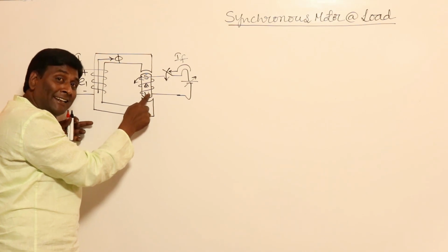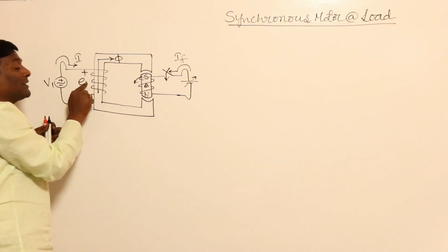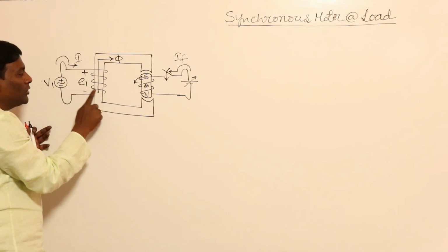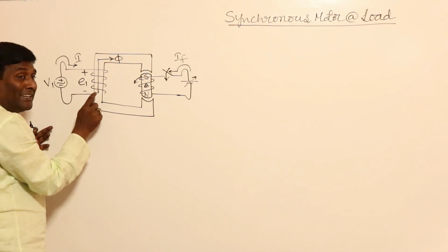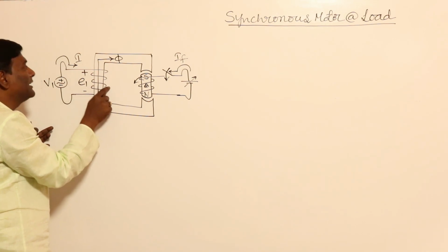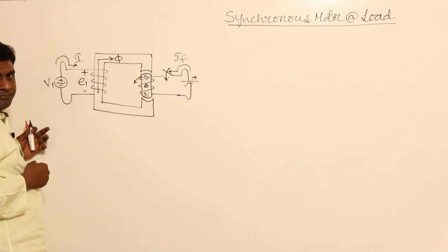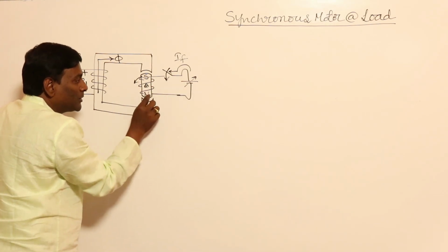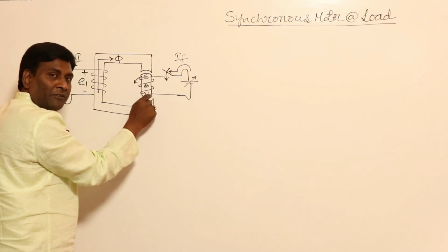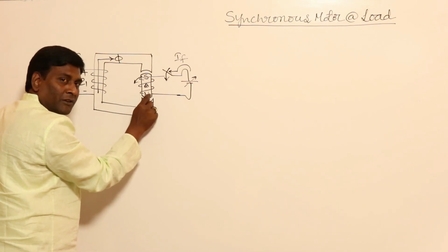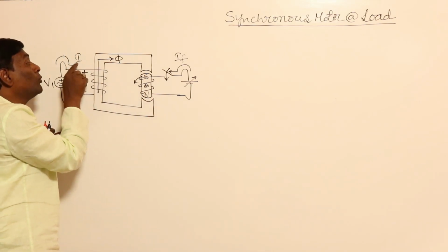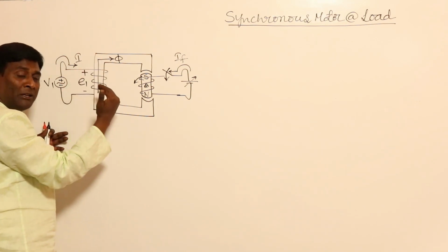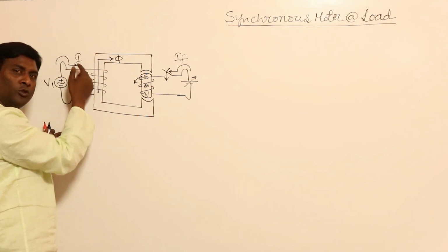Okay. So here 100 flux lines are required. 20 flux lines are created by this. So how many more flux lines has to be created by this? 80 only, because 100 volt, 100 flux lines. So in order to create 80 flux lines by this winding, my current will be reduced. Now, if field current is again increased such that this particular field flux is 50 flux lines, how many more flux lines has to be created by this? 50, only 50. Compared to 100, it became 80, now became 50. So current is going to be reduced.